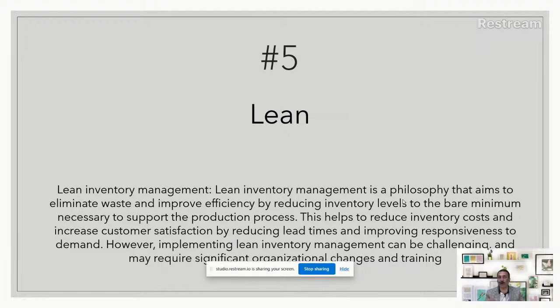If you know about lean management, even inside the production the machines are arranged in a cellular format so that there is no WIP buildup. Traditional organizations may have machines arranged as per job centers, like machining will be done in some place, assembly some place, testing some place, and the distance between these work centers could be huge, and thereby we are building inventory in the traditional system, whereas in lean, if you adopt the cellular concept, the WIP is reduced to a minimum.